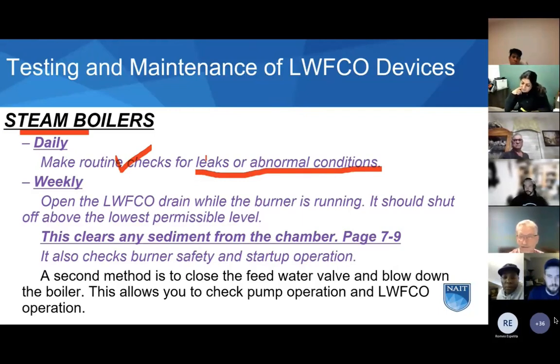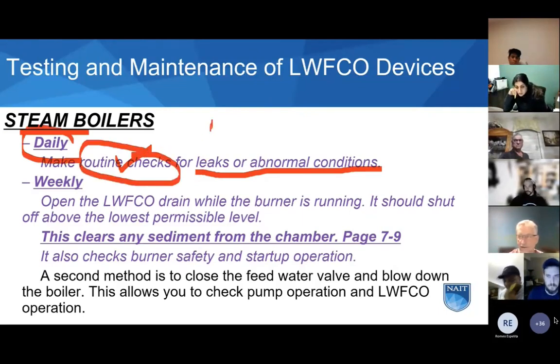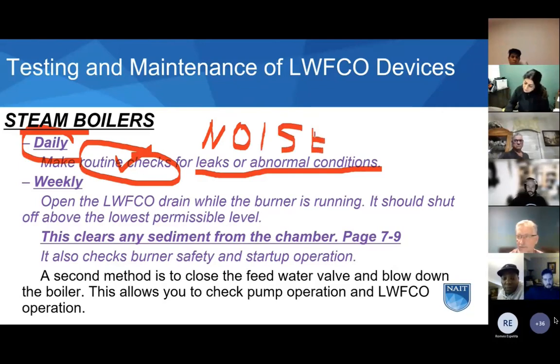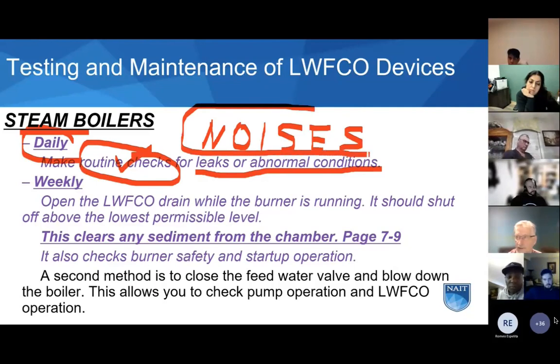Something that's usually missed when operators are doing routine checks or normal operation: use your ears. If something sounds different, there's probably something going on. If you're an experienced operator, you'll know what I'm talking about. As you get more experience in operating equipment, you will learn to pay close attention, even to the vibration. You go up on the boiler deck and it's got a certain vibration. If something has changed, that vibration can be different.